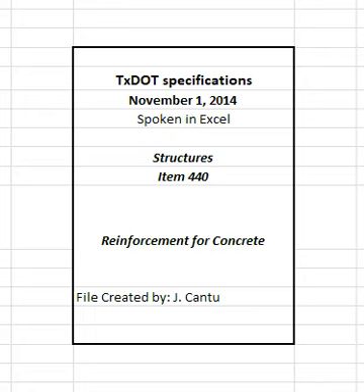The nominal size, area, and weight of reinforcing steel bars this item covers are shown in Table 1. Table 1. Size, area, and weight of reinforcing steel bars. See table in specifications. 2.3 Smooth steel bar reinforcement. Provide smooth bars for concrete pavement with a yield strength of at least 60 ksi and meeting ASTM A615.